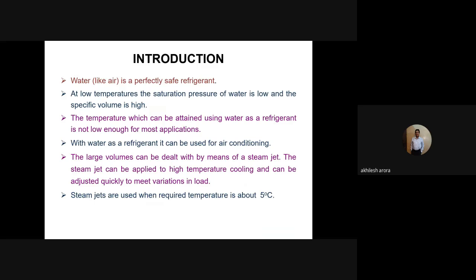Now let us proceed further. Water, like air, is a perfectly safe refrigerant. It doesn't cause any ozone depletion, neither does it cause global warming. So it's a safe refrigerant. At low temperatures, the saturation pressure of water is low and specific volume is high. So naturally, when the pressure is low, the specific volume increases.